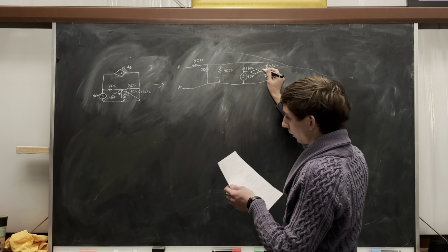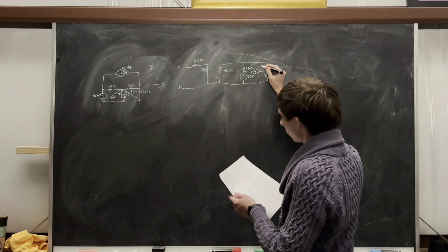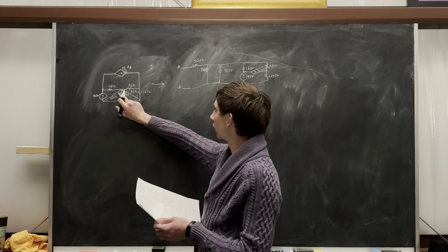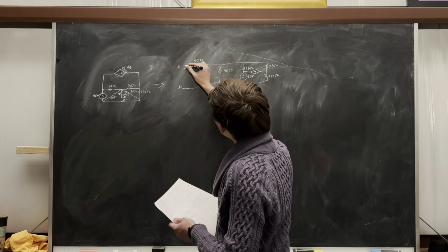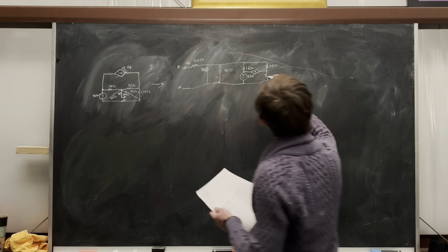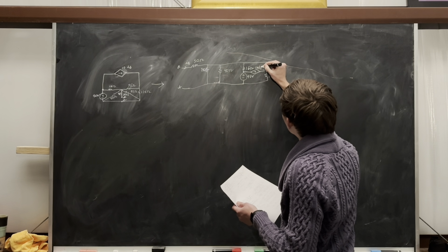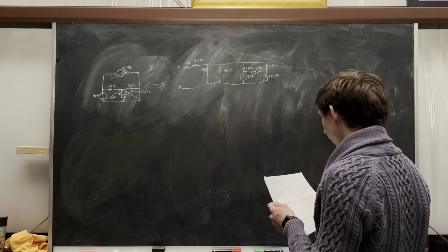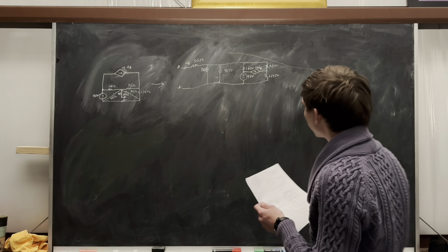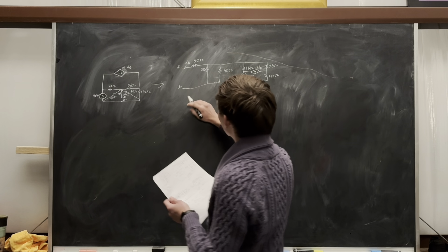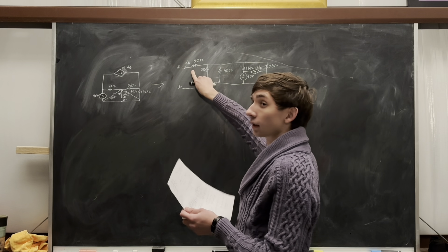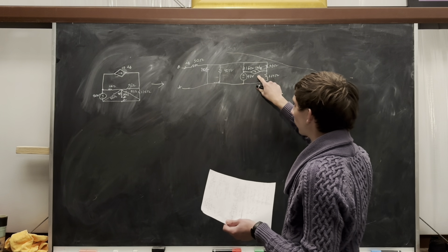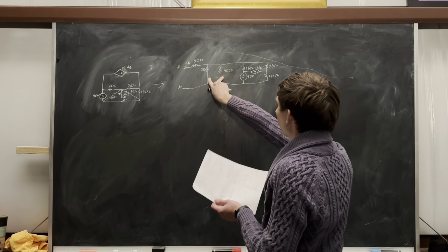Let's see, and it goes from this one. That's 10 I phi. It's drawn a little bit small, but I phi is the current going through the 50 ohm resistor here. So I phi. Over here we have 10. So when we're calculating V open circuit, these are just open. No current's going to be going through this 50 ohm resistor. I phi will be 0. This will be 0, so this will also be open. You probably already noticed that we can combine these two in parallel.